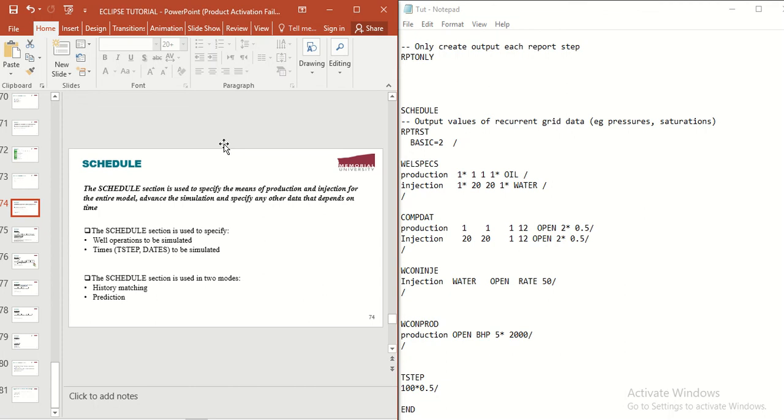Hello my friends. In this video I am going to teach you how you can write the schedule section of your data file. What is the schedule section? Basically, in the schedule section we are defining our wells. For example, if we have 5 injection wells and 5 production wells, in this section we need to define those wells, their location, their completion and their production or injection scenarios. As well, in this section we are telling Eclipse what our time steps will be and how long we want it to do the simulations.